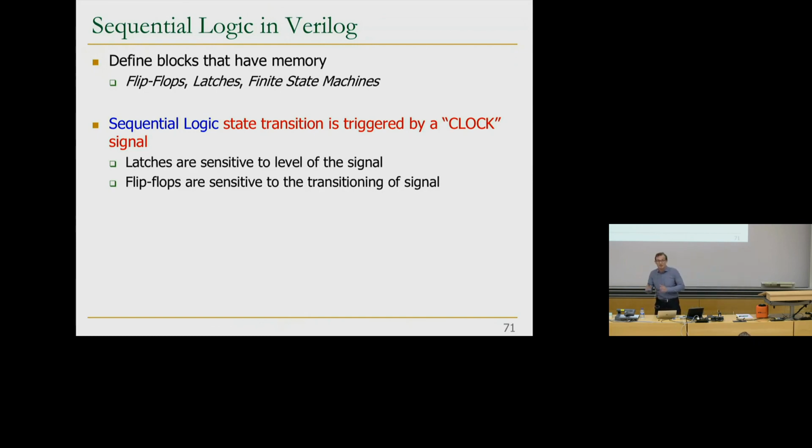But you will see this tomorrow because there's some overhead in terms of communicating the clock. Okay, so basically, we're going to trigger state transitions. Remember, the latches are sensitive to the level of the signal. If the signal is 1, then the latches will latch the value, and transparently.